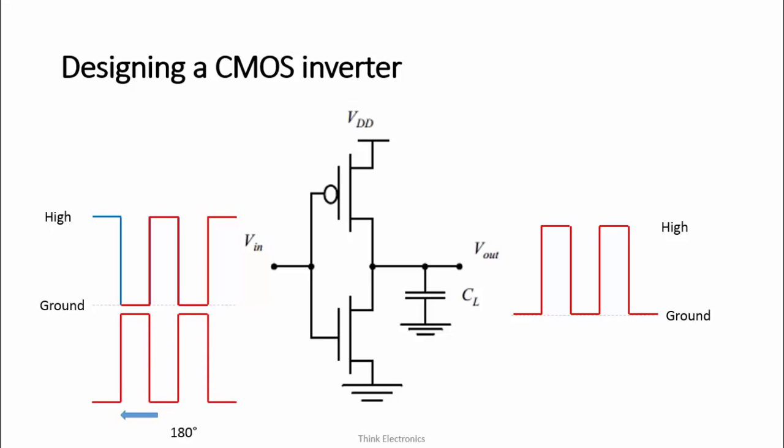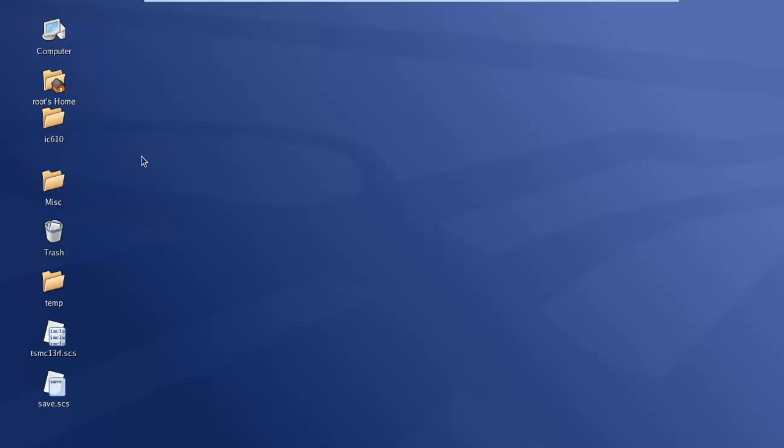Of course, this depends on many variables like the size of both NMOS and PMOS, the total power, the voltage headroom, and the value of output capacitance. For example, if the output capacitance is very high, the output voltage won't have enough time to charge and discharge its capacitance, and the output voltage will continue decrementing. If the output capacitance is very low, on the other hand, the output capacitance will charge and discharge very fast, leading to problems with the timing of the inverter output.